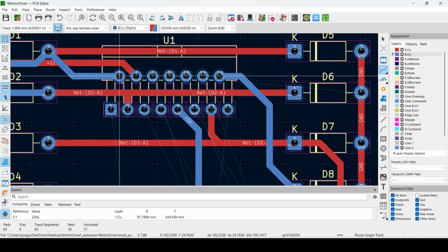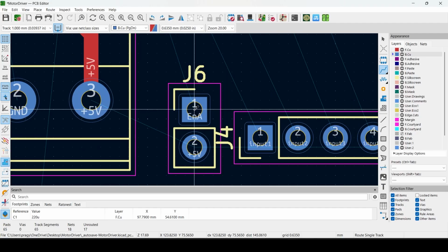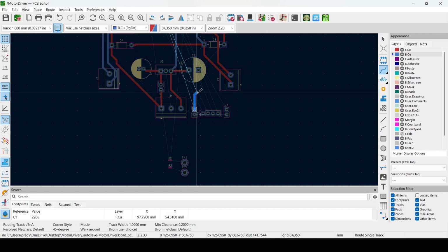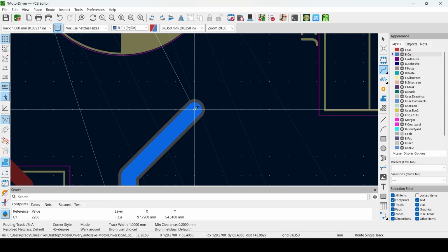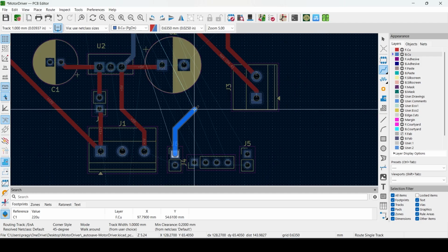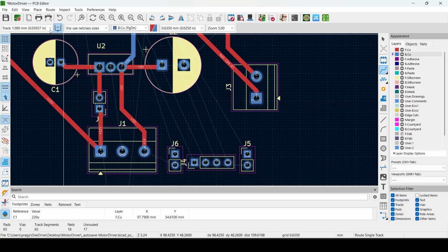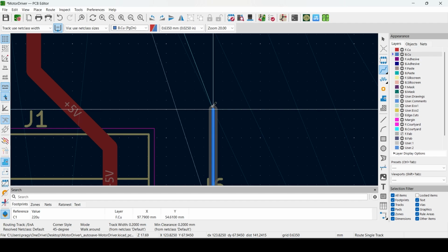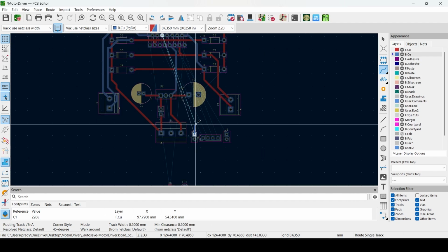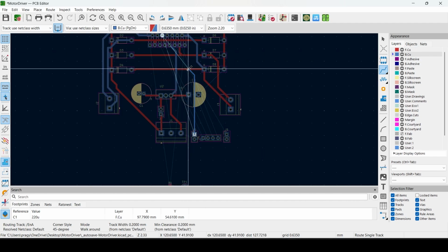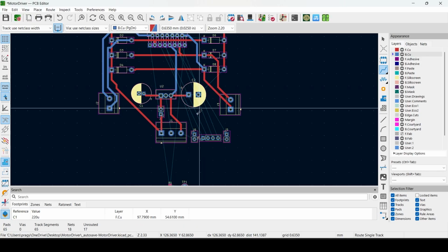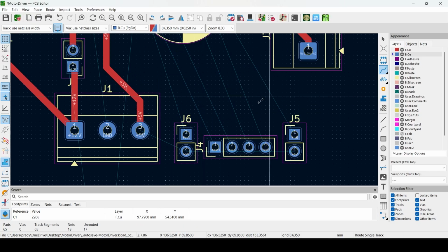Now let's try to connect our signal tracks. We have E and A here. Now you'll notice that for signals we don't need this 1 mm track width. So I'll quickly change it. If you click on use net class width, it will go back to this thinner width of 0.2 mm, which is sufficient for our signals. So I'll use that. I'm in the back layer now.